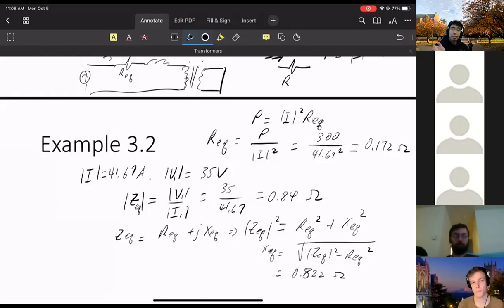Everything is 60 hertz. So just reading the sinusoid by itself doesn't help you with phase information. Everything at 60 hertz will be reading a sinusoid. To measure the phase information, you need a reference. You need a zero clock. Then you need to watch where things cross zero to get the phase information correct.